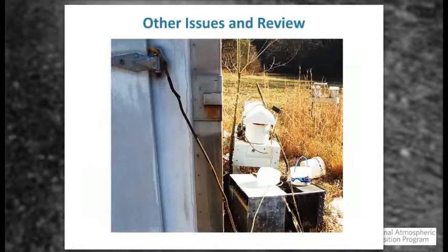Yes. Next, please. And then this is on line power, but you can see this is slammed in the door of a shelter. Again, just keep your wiring good, run it in conduit if you can. Just because it's low voltage, this isn't like Christmas lights you can string anywhere. Still use the same precautions and standards you'd use even for line power. Just because it's low voltage, yes, it's safe, but it doesn't mean it should be substandard.